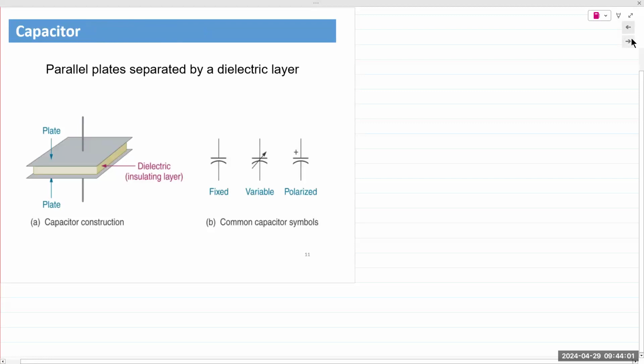Okay, capacitor. I will explain a little bit of the physics of how the capacitor works, but after that point, I will tell you to leave the physics on the side and think in terms of just engineering. Okay, so a capacitor is nothing but two parallel plates separated by an insulating material. It is exactly the same as well as opposite of an inductor. Many of the equations are exactly the same. The structure is the same, except the variables are changed. So we had the voltage equation for an inductor, that becomes the current equation for a capacitor.